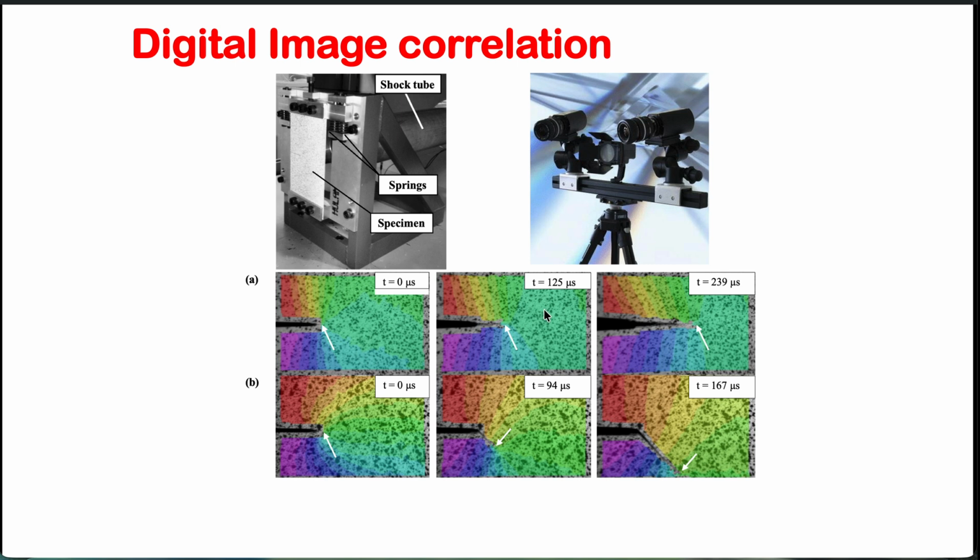As you can see, this is essentially a picture of how a crack is propagating through the material on a speckle pattern. You can see the crack propagation at different times, and you can see the strain field here, specifically how much displacement we are seeing as a heat map. Of course, these red areas are showing you the highest strain, and these greenish areas are showing you the lowest amount of strain. And the setup we have in the lab is essentially something like this.